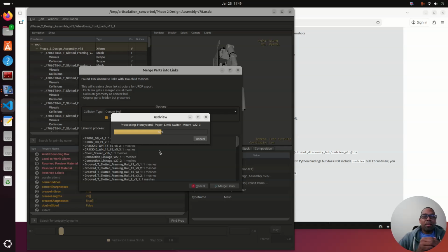We go sim to real to sim to real, which seems complicated, but the reality is it's quite simple. There's a simulator. We're using Isaac Sim and Isaac Lab. And then we also export and run the same things in MuJoCo. Then we run it on the real robot, meaning that we get back the metrics, the real movement of the real robot, how precise it can be. Some robots have a lot of play in the joints, and it's not very stiff compared to what we saw in the simulator. So we do a true up.